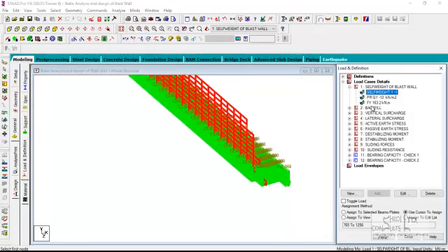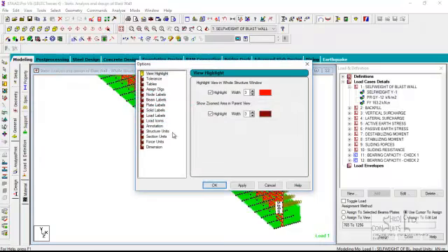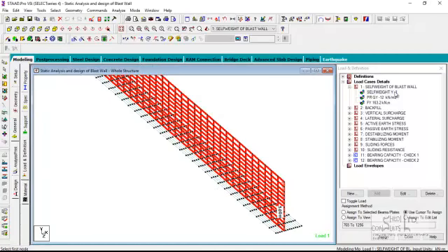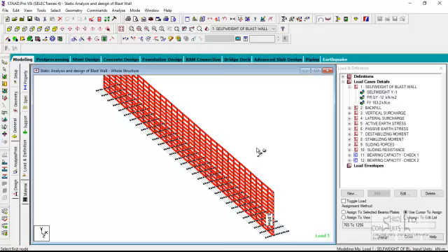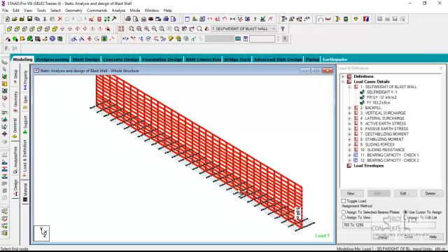So if you look at the self-weight, the self-weight was specified. Okay, so the self-weight loading, which is an automatic loading, was specified on the entire wall. Like I said, this self-weight loading has increased the load by that additional modeled height of 0.5. So we need to calculate a weight corresponding to 0.5 and apply it at the centroidal location of the total weight of this, right?